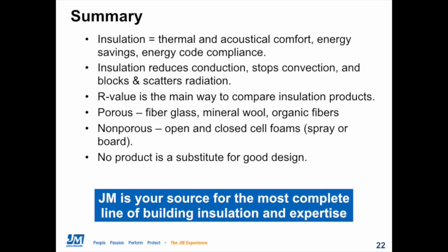No. I would say the short answer is no, there's not. Block walls don't care so much if they have a little bit of moisture in them. They have quite a capacity to hold water vapor. And so if the AP foil was used also as the drainage plane and the air barrier, very little water should get behind that, and any that did could then kind of work its way into the building. It could dry into the building from there. So no, there's no real concern with putting that on a block wall.